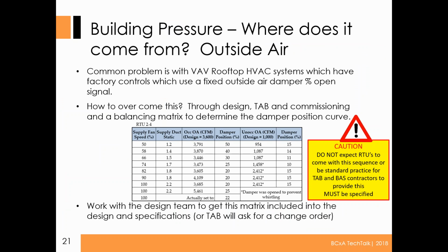Okay, so we accomplish this table by using the VAV boxes. To answer your question, this was not done in disregard to the actual system. What we actually did was we started with the system all the way down at minimum, so all the boxes were down at minimum, and that translated to right about your 50% speed. And then we opened some more VAV boxes, and we said, okay, great. We had the balancer with us, we had the controls contractor with us, and we were basically orchestrating and saying, okay, open some more boxes.